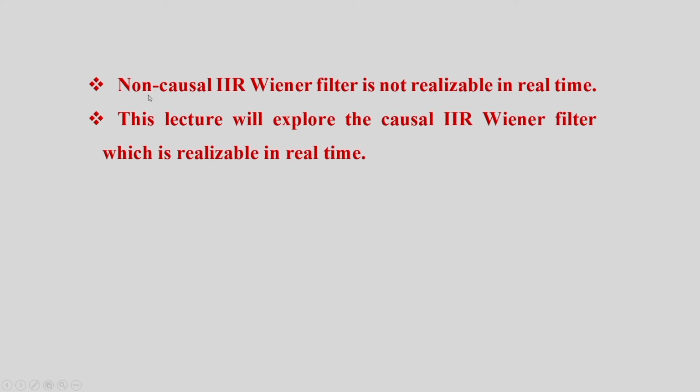The problem with non-causal IIR Wiener filter is that it is not realizable in real time. We cannot implement it in real time. This lecture will explore the causal IIR Wiener filter which is realizable in real time.